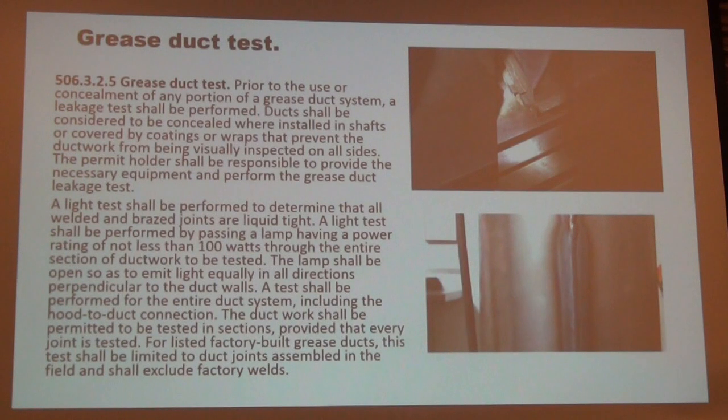Pardon? How if you would've got stuck? It was a huge duct. It was the main kitchen duct for the cafeteria. I met with Adam there, and he said, how are we gonna light test? This is up and it's a sunny day. Yeah, exactly. So what we did was they laid cardboard down because that duct was kind of greasy. And I just crawled through the duct and looked, and I didn't find any pinholes through it.